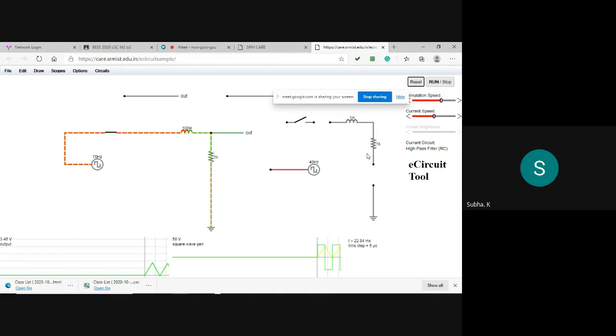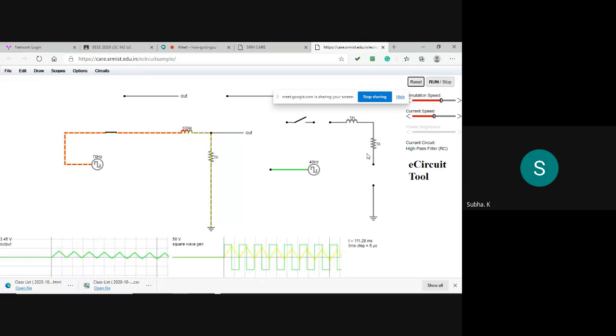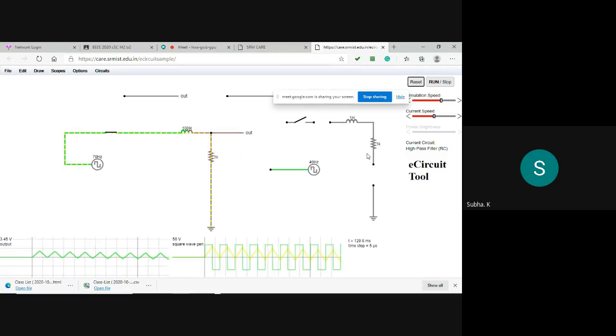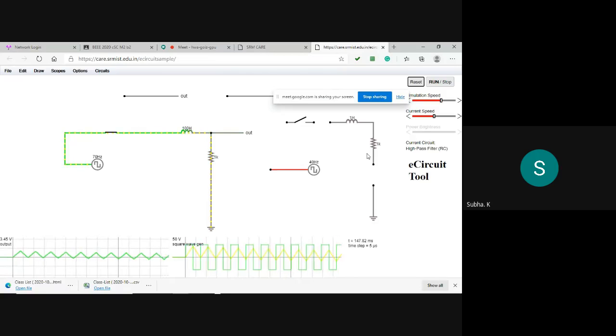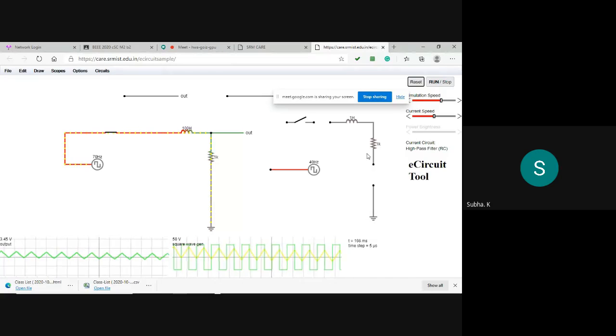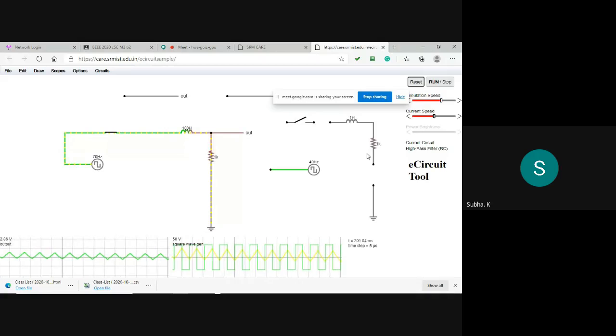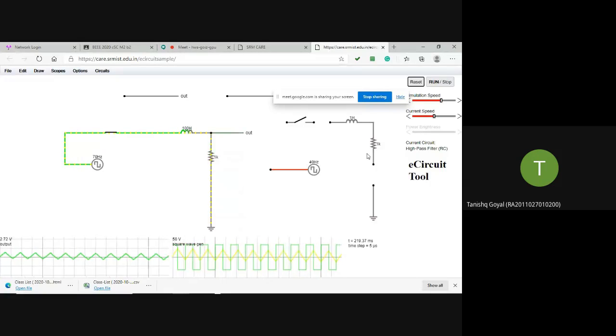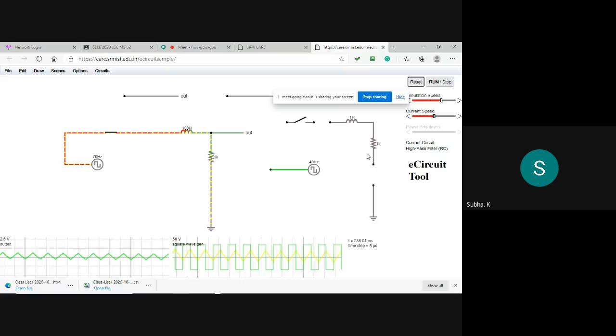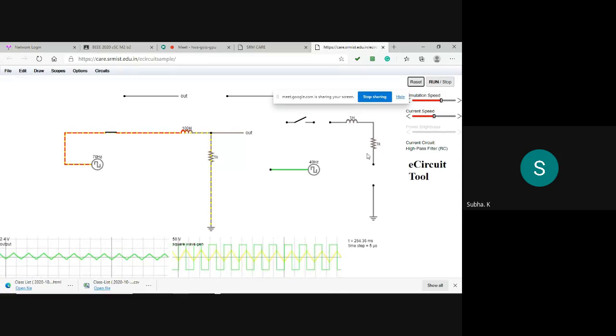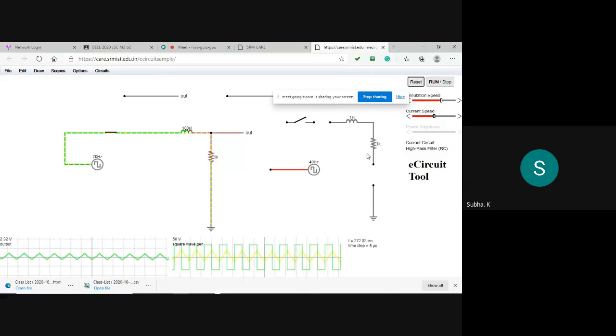Now you can change. You know what difference it makes? Now it becomes a triangle at the output side. Are you able to observe? Input is again square only, but the output, if you see, is resembling a triangle waveform. That will all depend upon what value of change I am making in the inductance. So, what value of change did I make in the inductance? Earlier it was 1, now I have changed it to 100 Henry. That's why that waveform is more short.